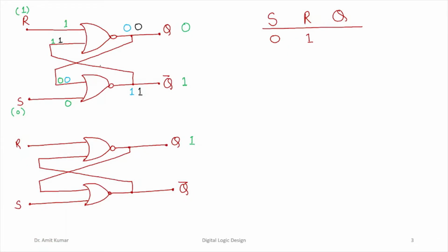If you look at this 0, from the feedback mechanism, it will be made available to this particular NOR gate, right? This 0 will be made available to the input of this NOR gate. So 0 NOR 0 is going to be 1. From the feedback, this 1 will be made available to the input of this. So 1 NOR 1 is going to be 0. So the final output Q will be retaining, fixed at the value 0.